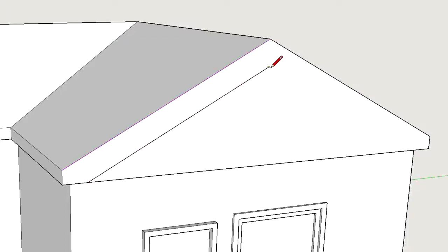Click to finish that edge, then continue drawing and hover over the far roof line to tell SketchUp that we are now interested in that edge. SketchUp will now show us the parallel inference to that edge and we can follow it down to meet up with the lower on-edge inference point. At this point, you can keep practicing on your own.